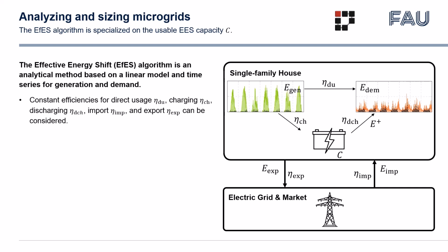And important for this presentation, those efficiencies are mean values. So if you have a varying efficiency based on some function or nonlinear relationship, you have to construct the mean value for your system. So typically run it for a really long runtime until it reaches steady state, cut transient state effects, and then calculate your mean value out of it.